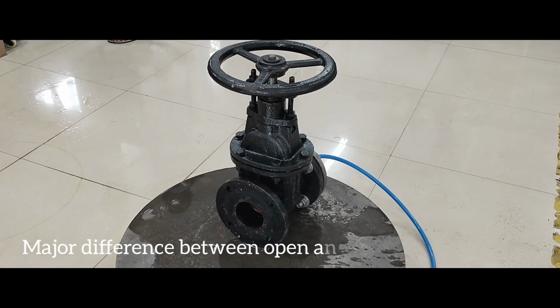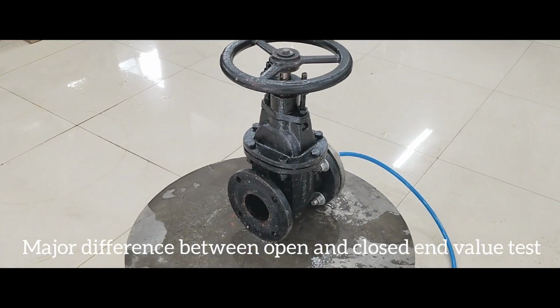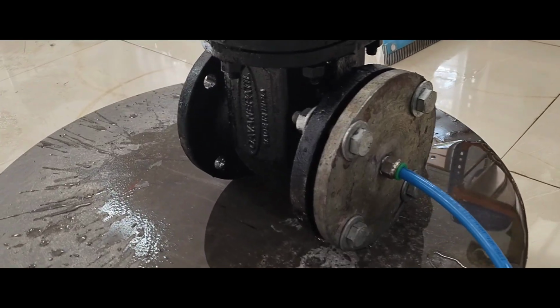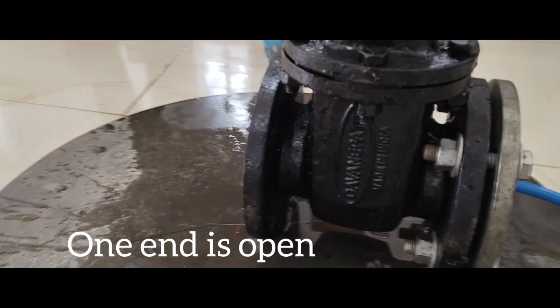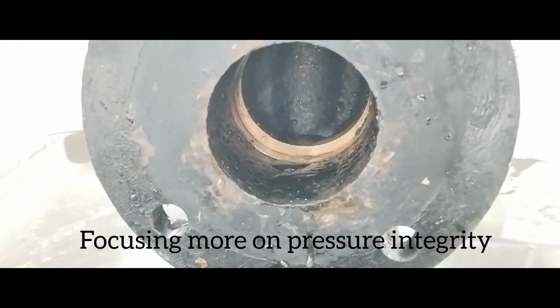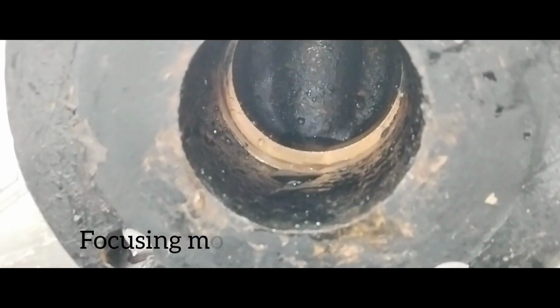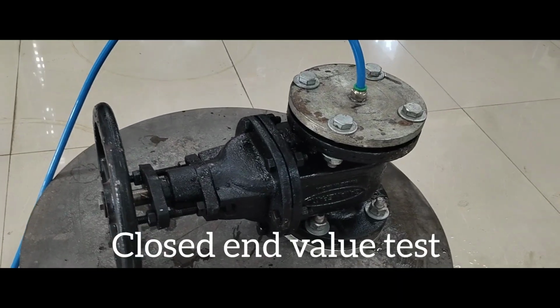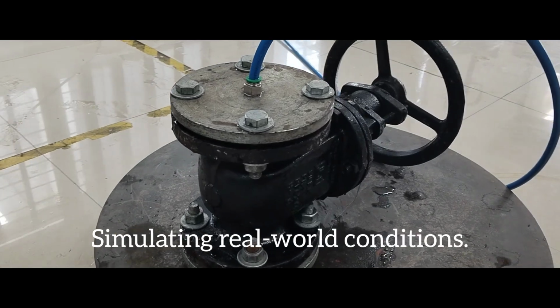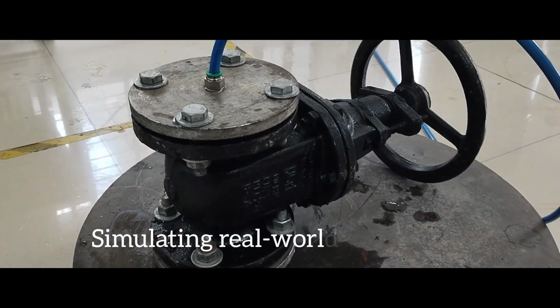The major difference between open-end valve test and closed-end valve test is that in open-end valve test, one end is open, which focuses more on pressure integrity without fully sealing the valve, and in the closed-end valve test, both the ends are sealed, simulating real-world valve conditions.